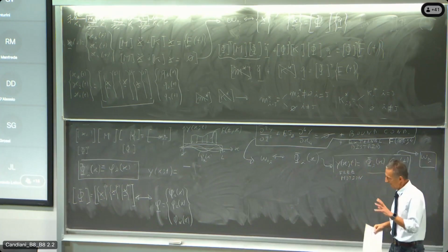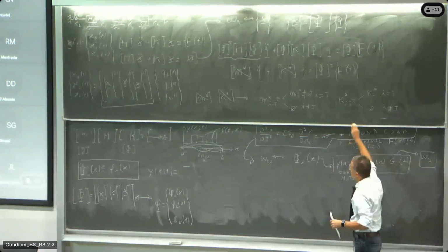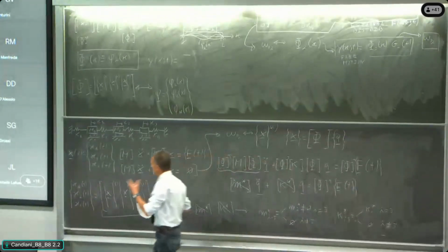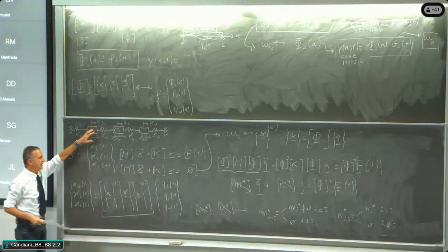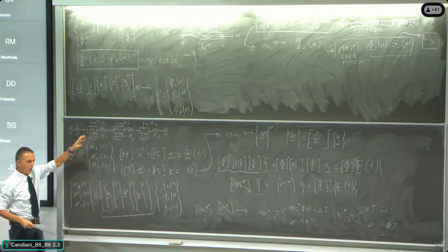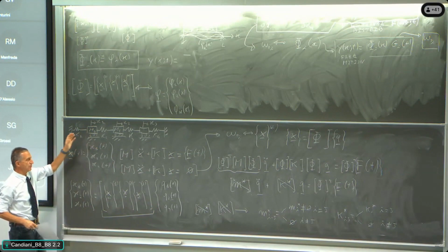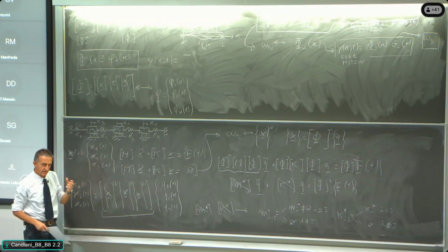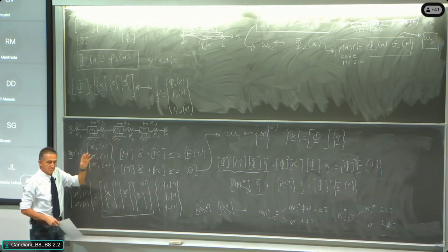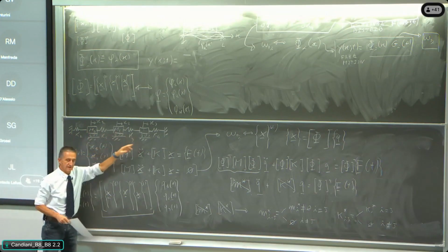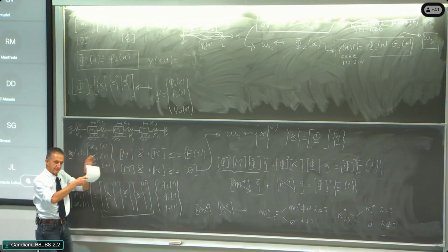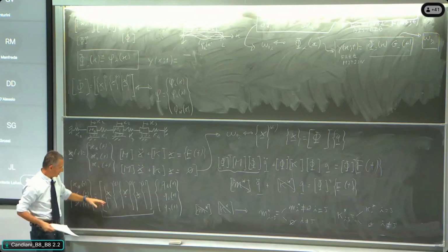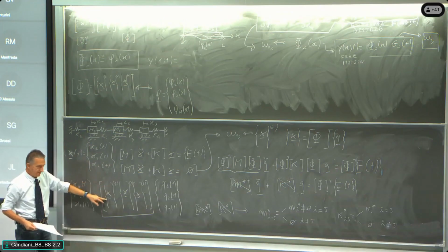Let's say we should have a practical vision. Here we have a mode shape where the three masses are moving all together to the right, for example, and this could be the first mode of vibration. Maybe the motion is a little different here and there, so the vector x1 could be 0.8, 1, 0.9.